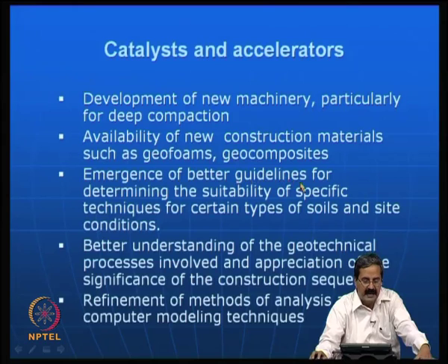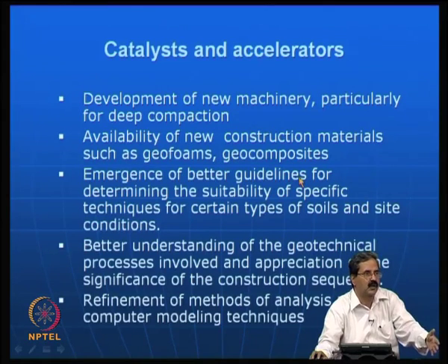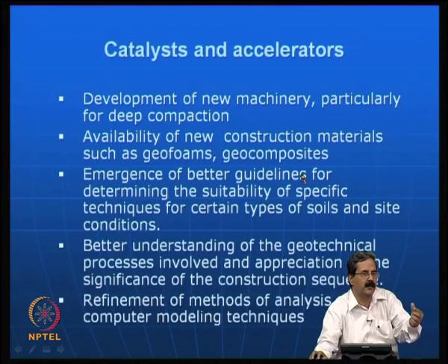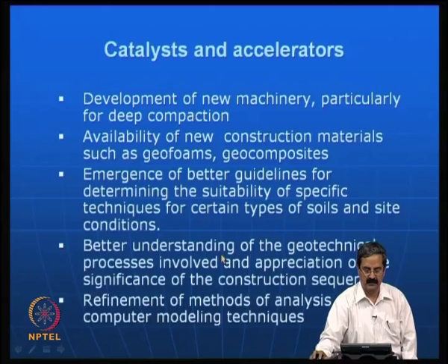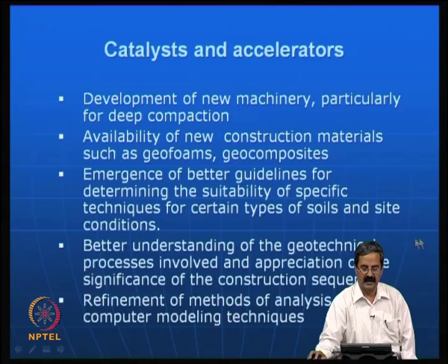So, if you do not have proper guidelines, or if you do not frame them, actually before you take up a particular project you should have guidelines first, like people prepare a feasibility study. Say for example, I am trying to use a reinforced soil technique here. To what extent it is feasible, what is its advantage, how it can be constructed, all these things will be coming in the guidelines. Okay. Then, site conditions are crucial, of course, it depends on the depth. Investigation should be very thoroughly done.